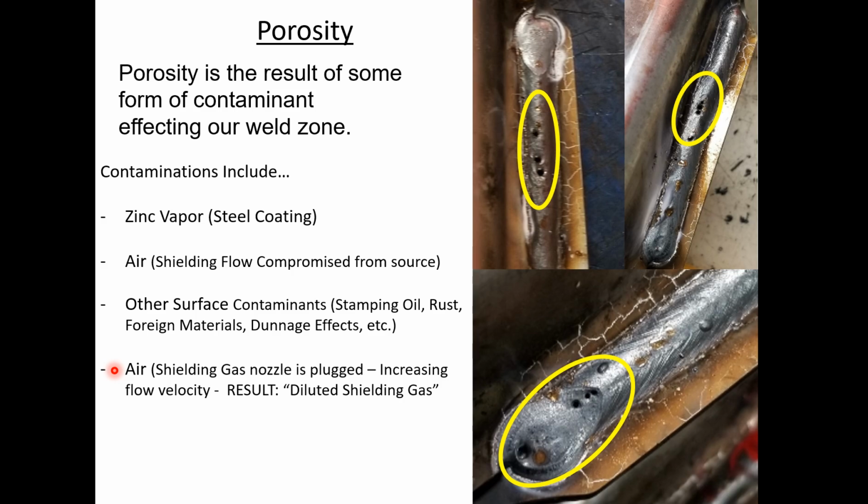My criterion for porosity when you see it is stop, especially if it's anywhere near the spec. Stop, clean the nozzle. Make sure the nozzle's nice and clean, and then start again and observe. There's a bunch of reasons why you might continue to get it, but let's make sure we've got a clean nozzle first. The spatter will sometimes go up inside the nozzle and cause disruptions in the gas that cause those issues. But I always say, step one, clean your nozzle, keep going, observe.